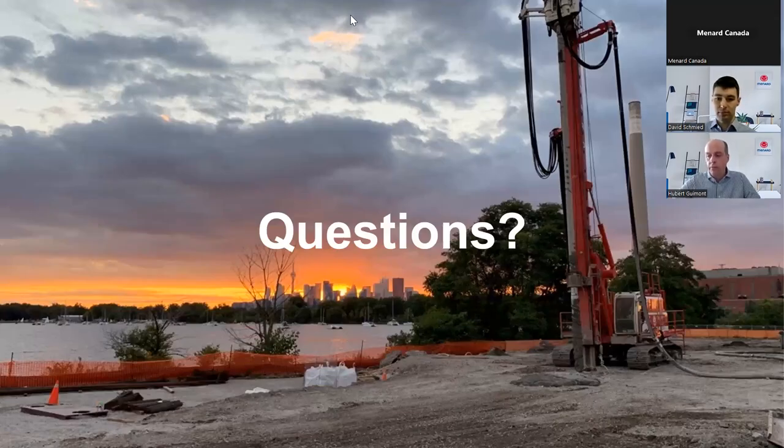Vibro compaction, vibro densification as well, generates a bit of vibration, not much. Soil mixing is vibration free, basically. But still, you need to make sure that you're not remolding too large of a zone. You need to think about that with the curing time and sequence. If you're going into a very sensitive zone, you need to make sure that you have a very safe working platform, and also that you're sequencing your work to make sure that you're not lowering the safety factor unreasonably.